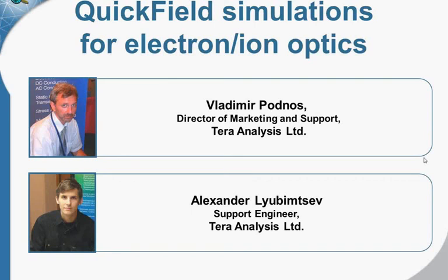You may use a built-in tool for charged particle trajectory in 2D electrostatic postprocessor of QuickField. You may use our free utility as is or modify it and simulate the particle trajectory in electric or magnetic field. Or you may use a specialized third-party software which may import the field calculated in QuickField and perform further trajectory analysis. Choice is yours, and our support team will be happy to help you following any of these directions.